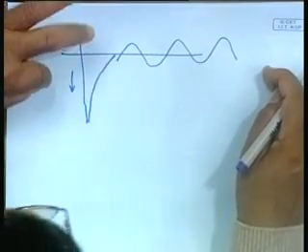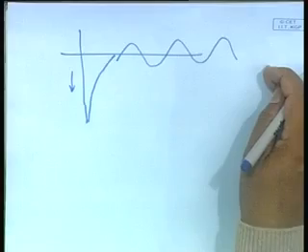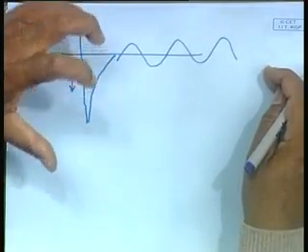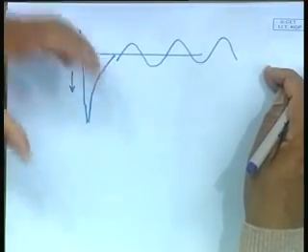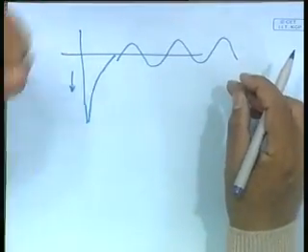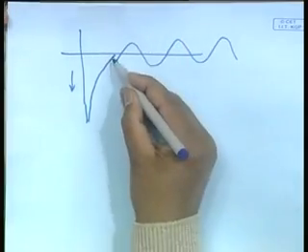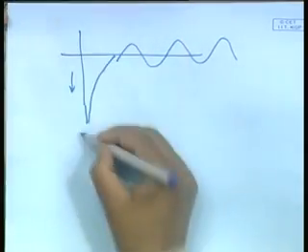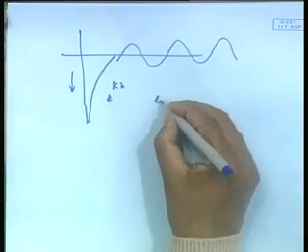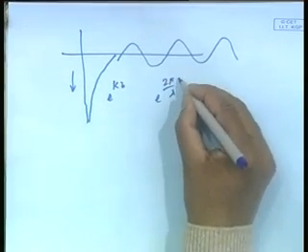This is very important, because we will find out afterwards, when I put a shape here, obviously it would also respond to this harmonic excitation, like something is being pushed every 10 seconds. So, it will also have that every 10-second oscillation. This is extremely important for water waves, that things come down exponentially. How does it come down? With e power of kz. What is kz? E power of 2 pi by lambda into z.